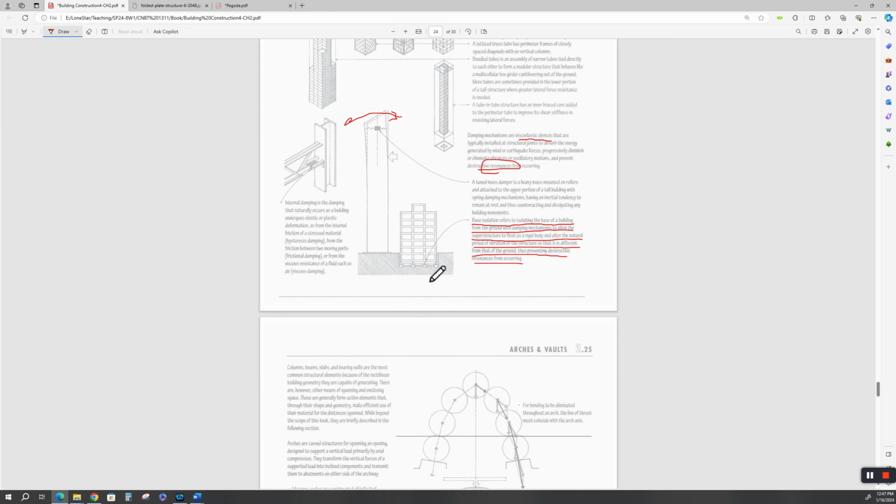they isolate. You're isolating. Now, these things are huge elastomeric pads. We use them on bridges. They're huge elastomeric pads. The bridge beam would set on that, and the load would go across the top. You'd have a peg going through there, a pin, and then this is pinned into the support mechanism. And it allows this to move, and any vibration from the road flexing is dampened by the elastomeric pad, and it allows it to move up and down.